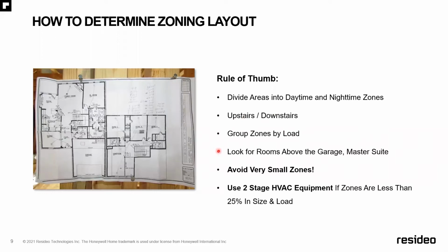You also want to pay special attention to rooms that are above a garage. This can present some extra special challenges because, depending on whether the garage is heated or not, you can potentially have three exterior walls, obviously a hot attic, and potentially a cold floor. So lots of heat loss and heat gain can come from that.